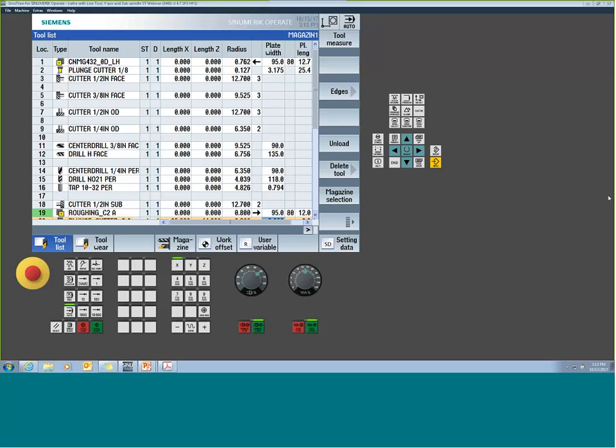How would we distinguish the spindles in our program? Oh, I'm assuming you're talking about from the G-code side. I'd say that the best scenario there, go back and take a look. I'm pretty sure I did a multi-spindle webinar for G-code. But what happens is you get some set main spindle commands come into play when you're jumping between your spindles. There's some slightly different protocol where you map what S code and M code goes to what spindle. So you have to know the number of the spindle. But I did do a webinar on it, so check it out. I think you'd find it quite helpful.